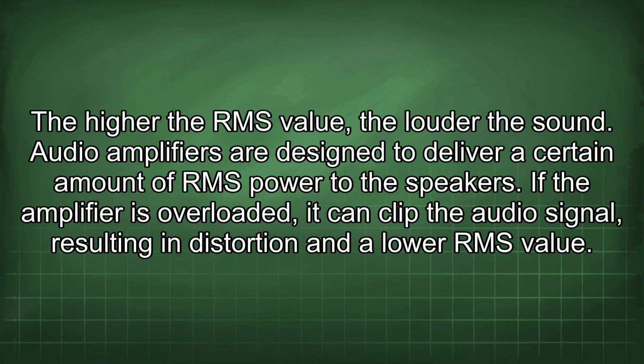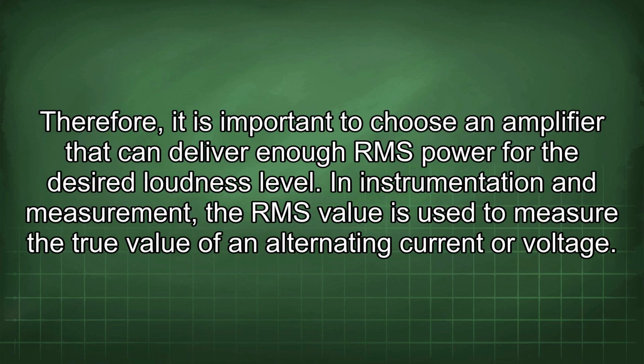If the amplifier is overloaded, it can clip the audio signal, resulting in distortion and a lower RMS value. Therefore, it is important to choose an amplifier that can deliver enough RMS power for the desired loudness level.